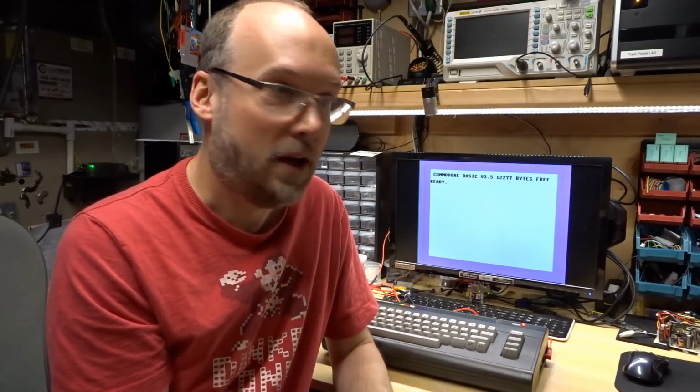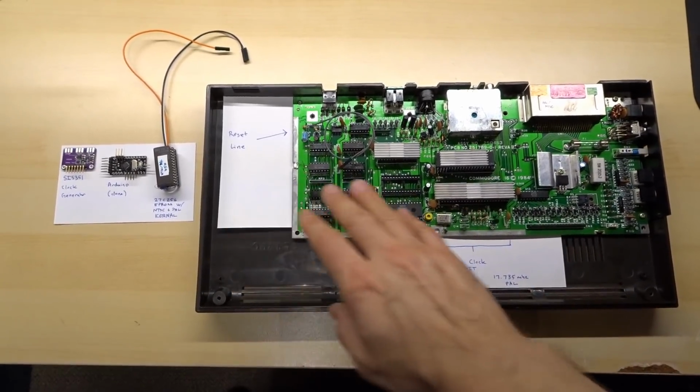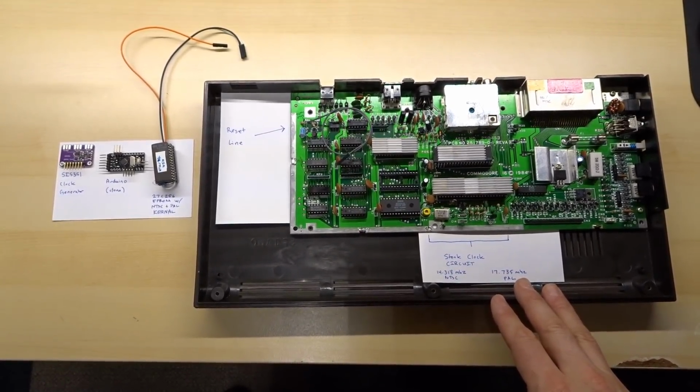So similar to the Commodore 64, the C16 uses a crystal oscillator to generate the video signal and determines whether you're going to be able to run in PAL or NTSC. So let's take a look at how I perform this trickery by simply pressing the reset button to switch between two different clock frequencies. Here's the C16 with the lid removed. I have shown here all the parts I need to do to mod it. Let's take a closer look.